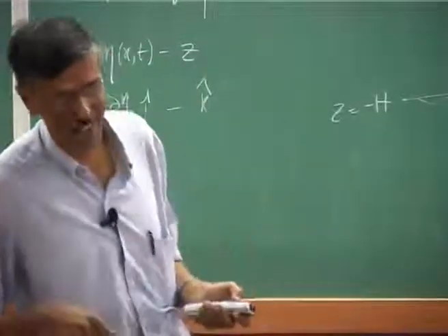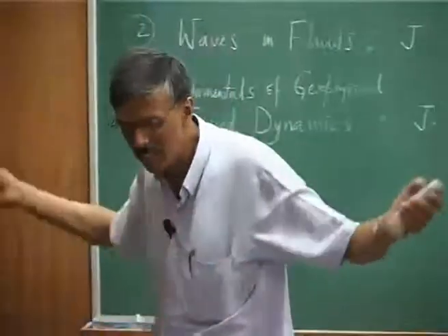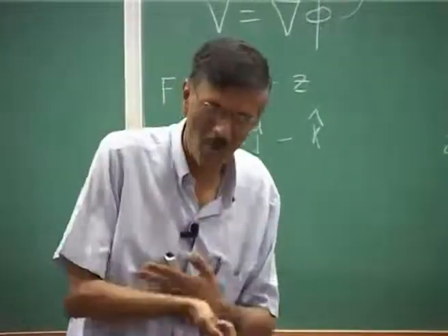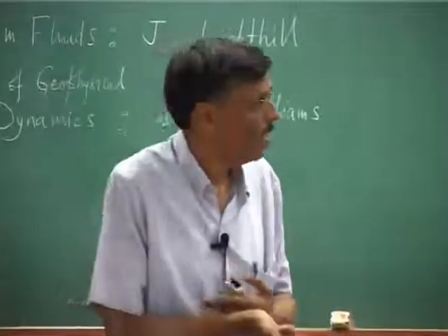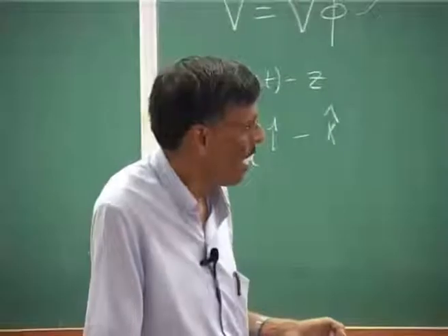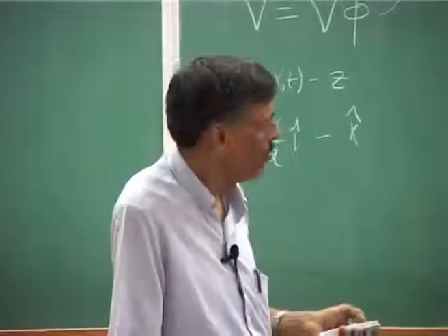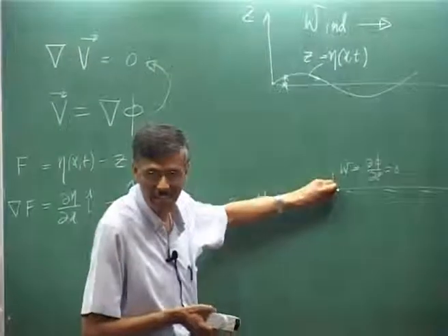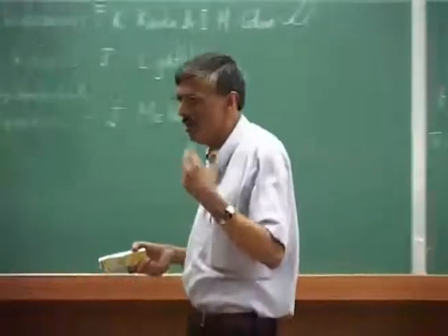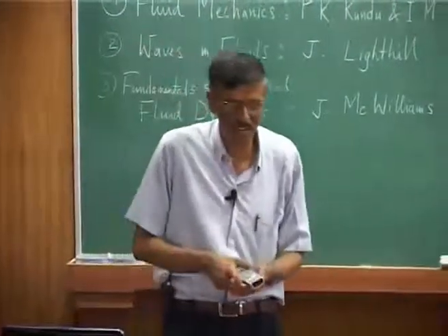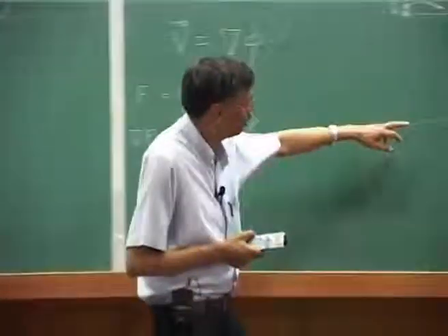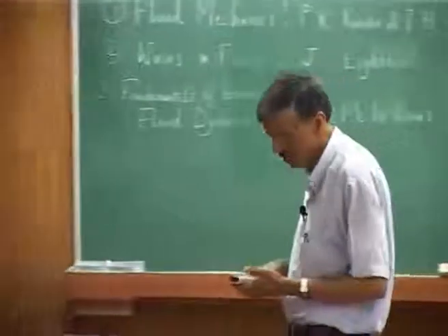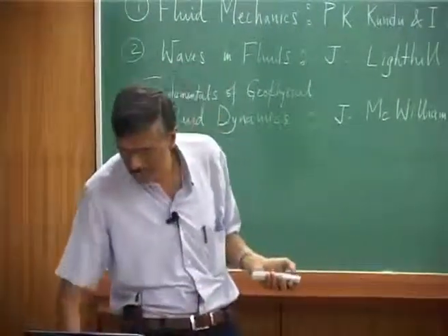So, what we are looking at in a sense is an unbounded domain in the x direction, and we are looking at a system which is not visited upon by losses because viscous terms have been omitted. Okay. So, we can afford to take a very large domain, and then we can look at the dynamics of the flow in the z direction, and that is why we are struggling with getting some condition here, some condition there. So, in the back of our mind, we are thinking in terms of some kind of separation of variables, and that is why we are looking for two sets of conditions, one at z equal to 0 and another at z equal to minus h, right. That is what we are going through, and you are seeing that it needs a little bit of care here.